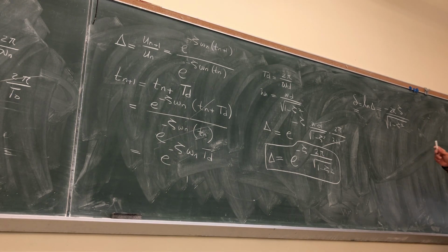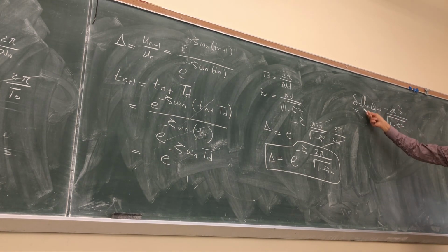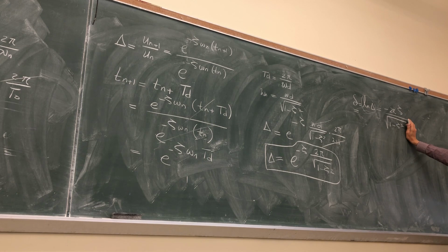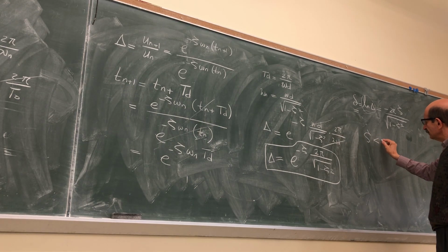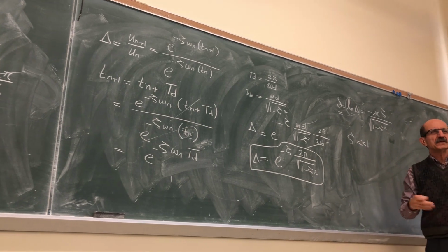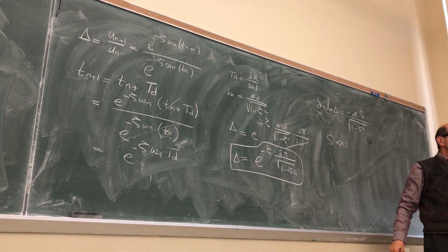As you can see then, by just measuring the ratio of those two and taking its logarithm, you can find the damping ratio in the system. This can get even simpler, because for the vast majority of systems, whether mechanical, structural, and whatnot, zeta is much smaller than 1. Let's say 10%, 20%, even 30%.